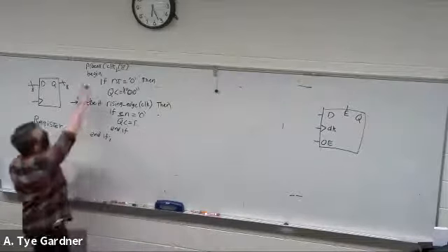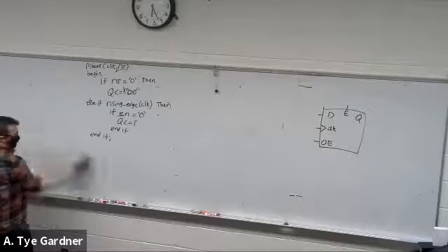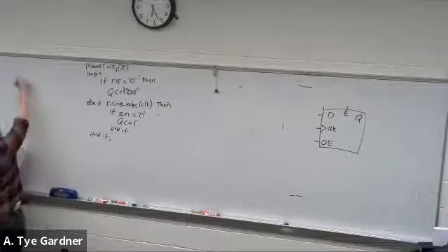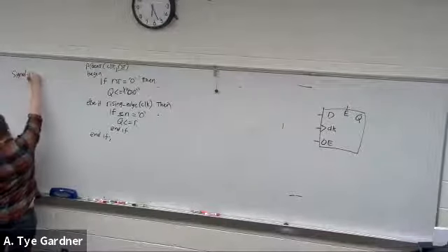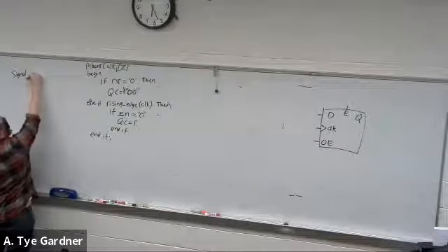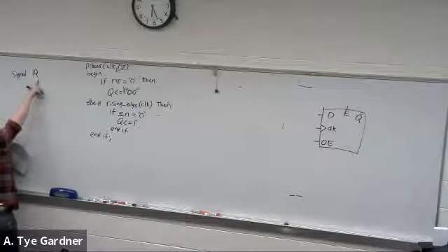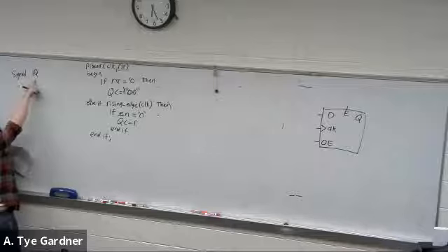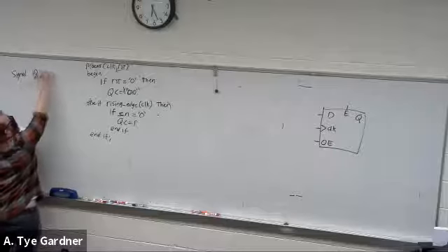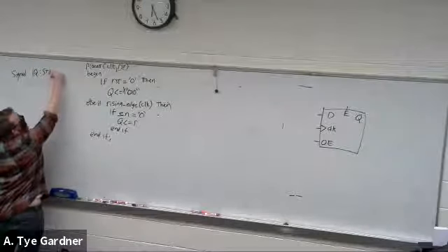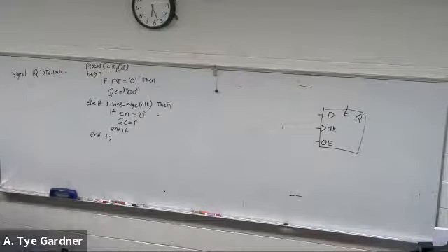So outside, before this process, inside of the architecture, I'm going to create a new signal that I'm going to call IQ, just to be funny, internal Q. So I'm going to use this inside of the Q block only. And it's going to be a standard logic vector of the right size. So I have this IQ.